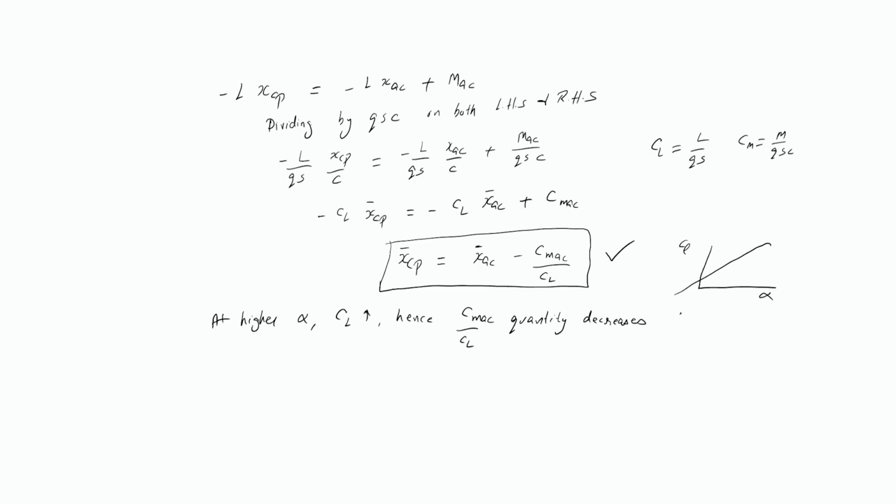And what happens if this term is decreasing? That means your center of pressure is approaching the aerodynamic center. The aerodynamic center is a fixed point, please remember. So as CL is increasing, the center of pressure is approaching the aerodynamic center.